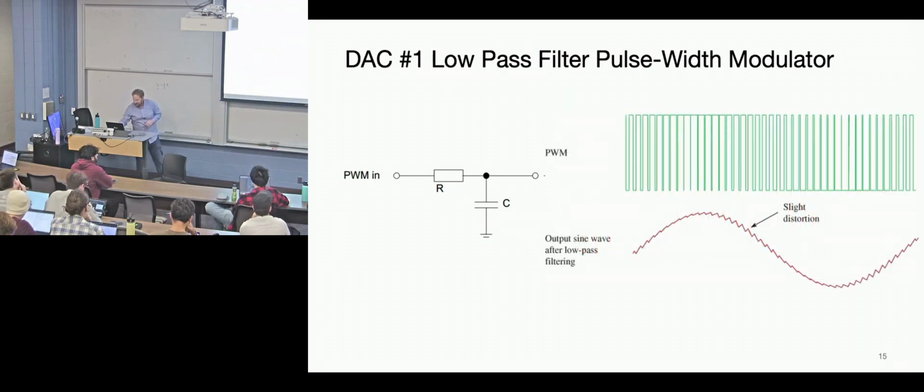So this is probably a better example. Here you see that the average is very high, we're nearly 1 all the time, maybe a 99% duty cycle, and then the voltage output is high. And then here the average would be closer to 0, and now the voltage output is 0. The problem with this type of DAC is that you always get this noise in here. It's very hard to get that ripple out. You could put a second order filter, a third order filter, but at some point it's just better to use the correct DAC. Any questions about this one?